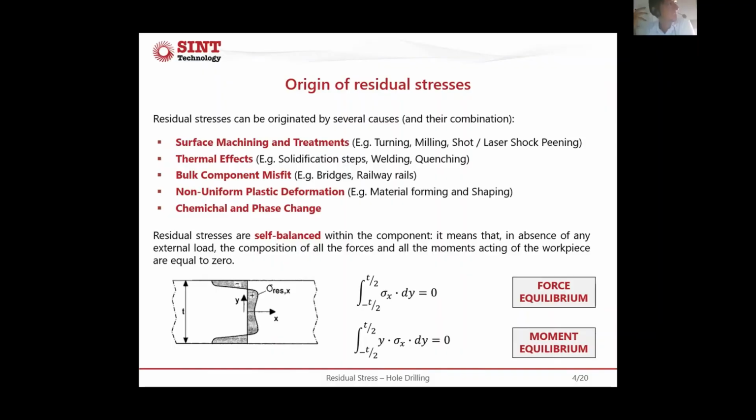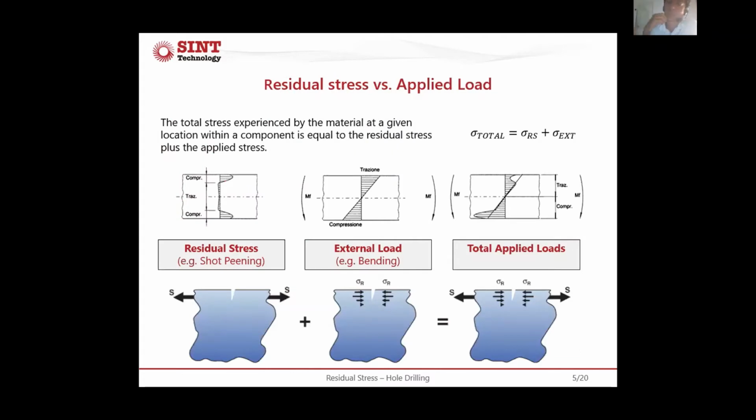Generally, the residual stresses are self-balanced within the component, so we always have equilibrium globally in the component. But on the other hand, we also have to take into account that the total stress experienced by a material at a given location and depth in the component is composed of two important contributions: the external load plus the residual stress, the internal stresses that I have.